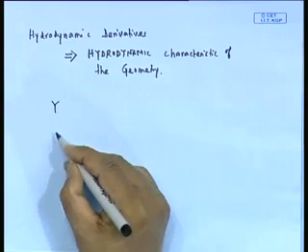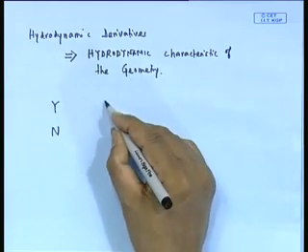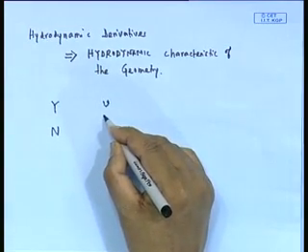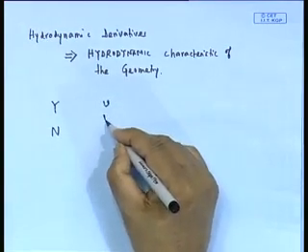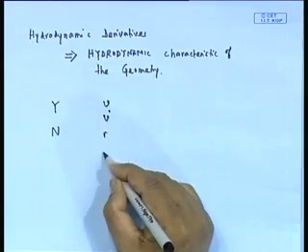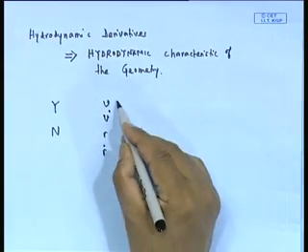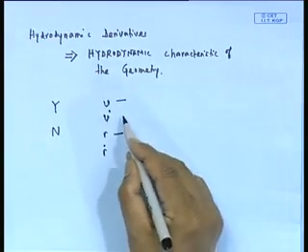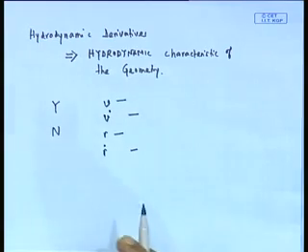Added mass, we will come to this in a minute, they are all characteristic of the hull. So, this is what is called the hydrodynamic derivatives. Now, how many have we got? Remember, in these two planes I have got Y, I have got N, and this side I have got V, V dot, R, R dot. This is velocity, acceleration.